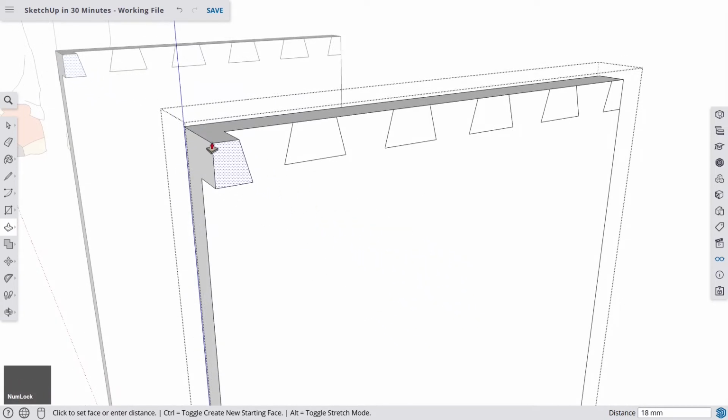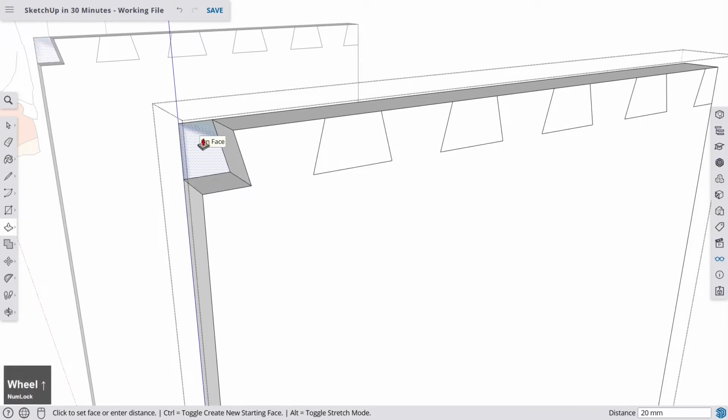We want to delete now this space that's not part of our dovetail connection on the pieces here. So we can do this by really pushing it back. And then you see this gray area here. You see that it looks a little bit strange and it says on face. And if you click now, it's gone. So we're doing the same with the other empty areas as well.